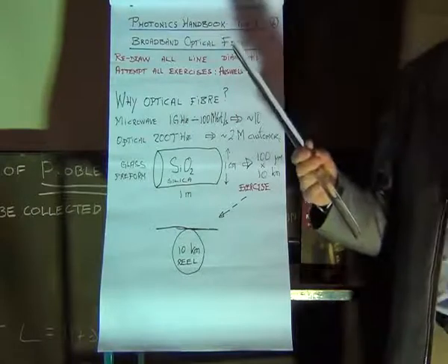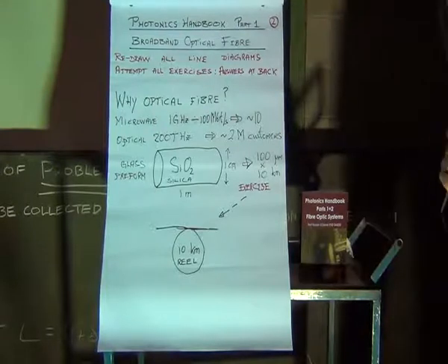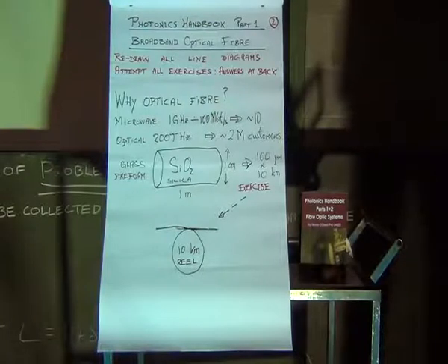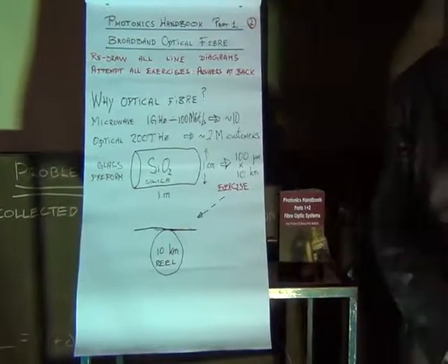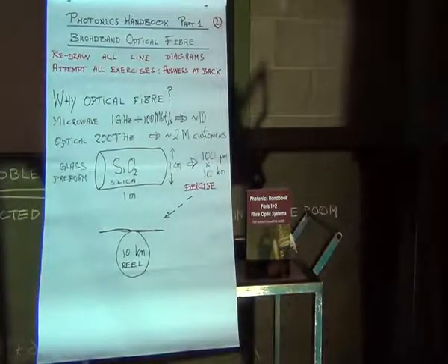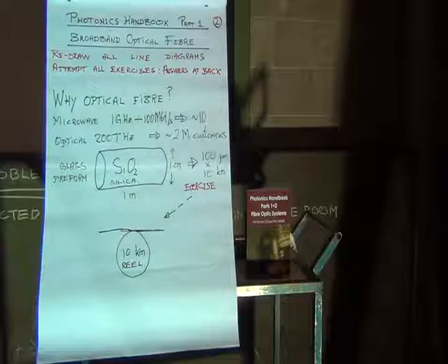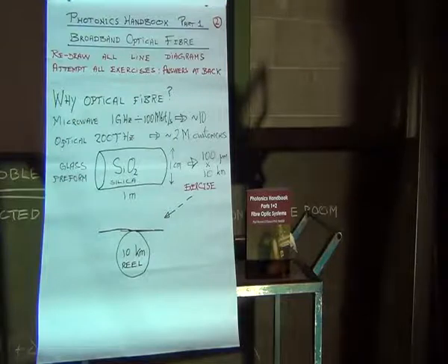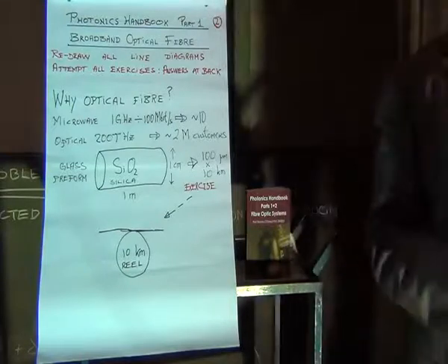And for once, when we try to turn the preform into a reel of fiber, nature is on our side. Because you mount this up on the top of a tower, and again you heat it with perhaps a radio frequency heater, and you draw a thread. Draw the thread down onto a reel and keep turning the capstan reel at a perfectly constant rate. And you'll end up with 10 kilometers of the 100 micron fiber. But where nature is on our side is whatever kind of refractive index pattern is in our preform reappears in micro miniature in the fiber.